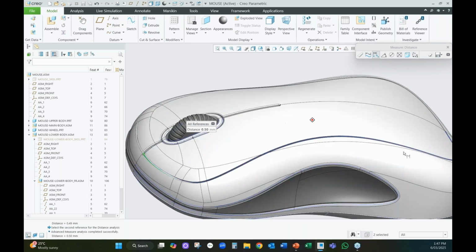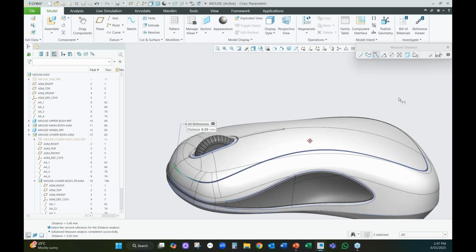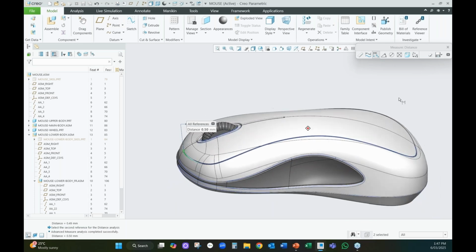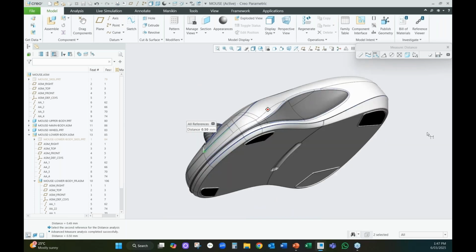And so that's certainly a big advantage. When time's running short and you need to release these files for tooling, you have confidence without having to interrogate every iota and every minute facet or detail of your assembly. I just know that my part lines are fine, so I can then go and check for other interactions and do your interference checks and your mass properties and your wall section checks as you should always do.